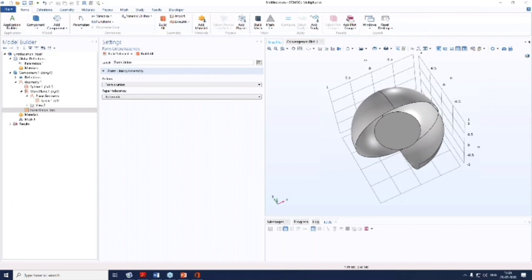Yeah, I got the error message that I was using too many steps. I should reduce the steps and try again. I think it was because I made different cylinders for each of the holes. Yes, correct. As you had used one step to create each of the cylinders, the number of steps to create the geometry was really very huge.